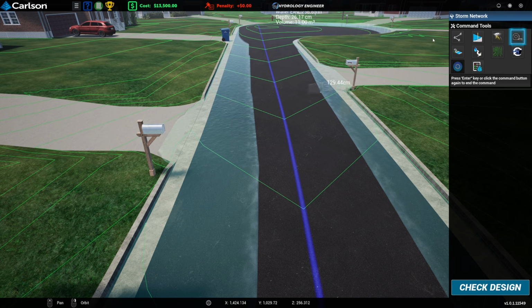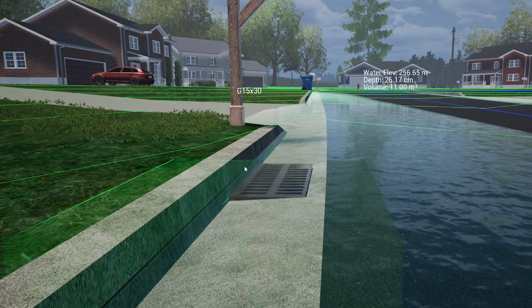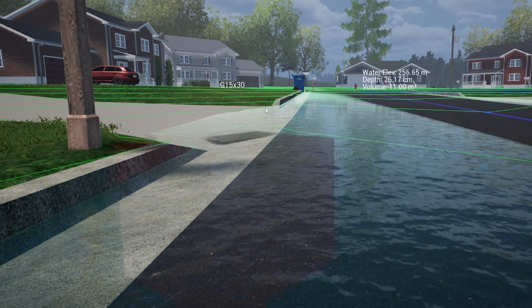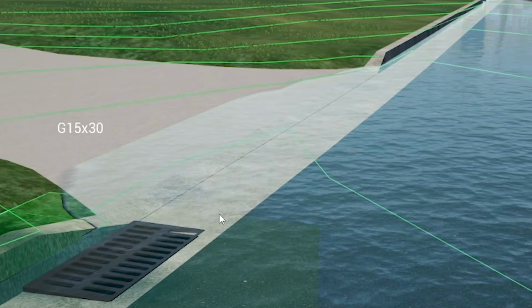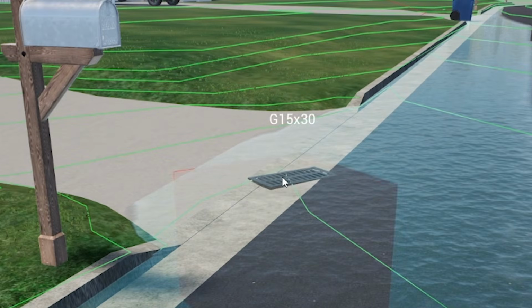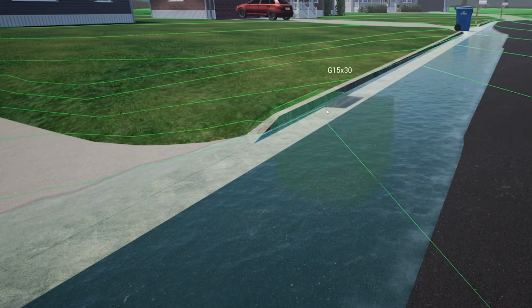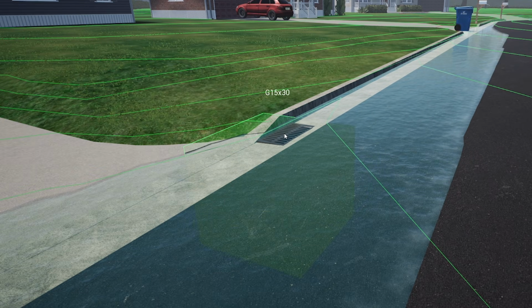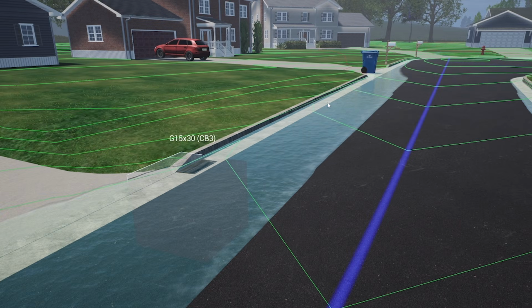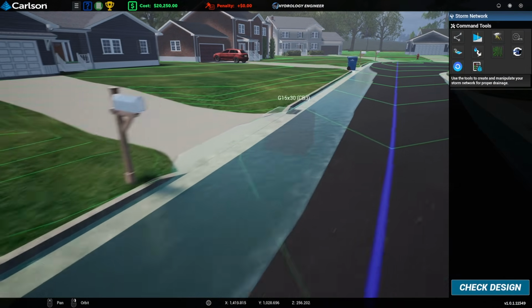Now, because that is a driveway, there's no curb upstand. A curb upstand being this vertical face of a curb. You can see it's a dropped curb there so that people can get to their drives. So we can't actually put a gully there because it won't work as well. Most of the water will go around the gully. So you always want a vertical upstand. So I reckon let's just put that one just upstream like that. So then all of this water here, this massive flow width, it should reduce down quite significantly into here. Granted, some of it will still flow past.